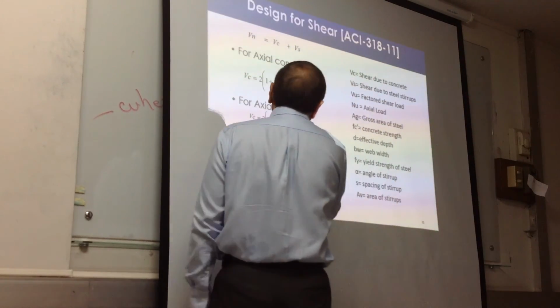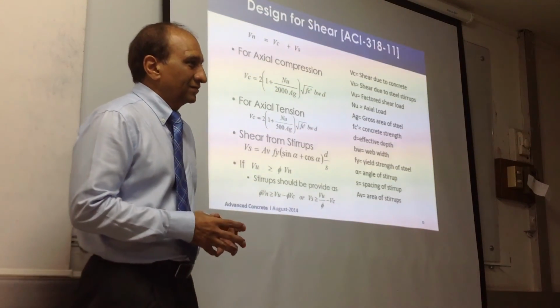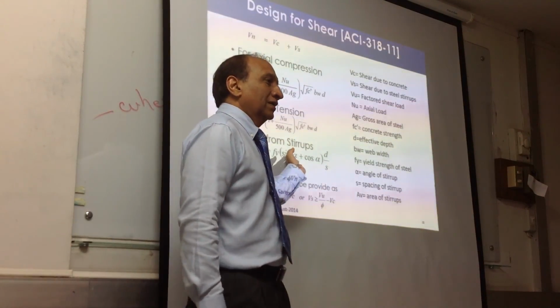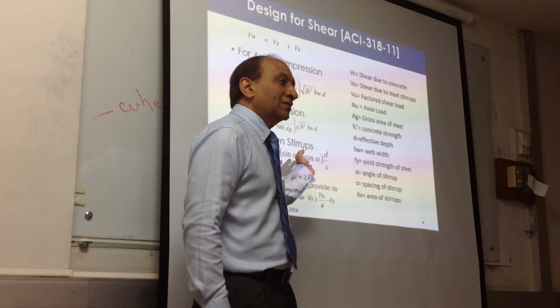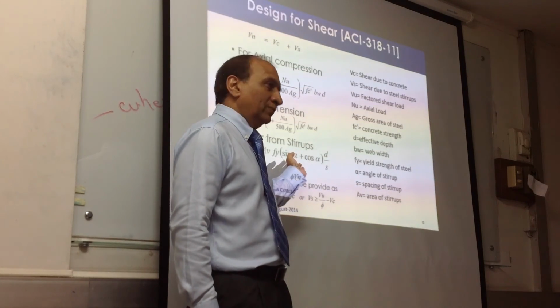And normally we use Av fy d over s because we assume a 45-degree angle. But it's not true. This is only true for pure shear. It's not true for other locations. But we assume it to be true everywhere to make it easy for us.